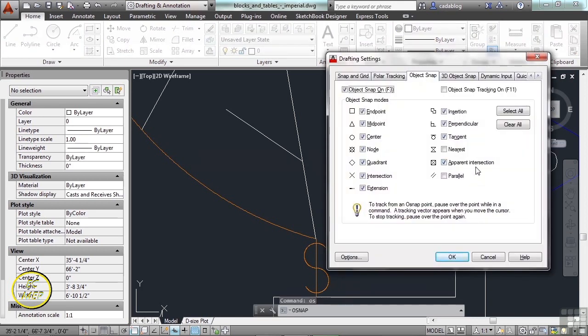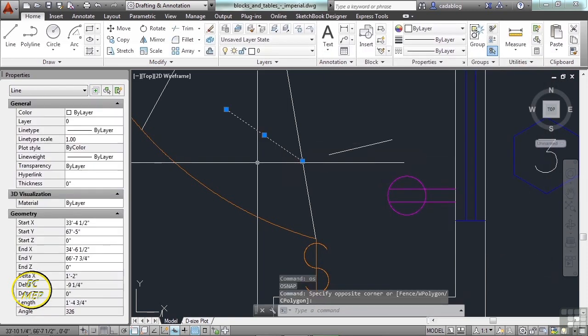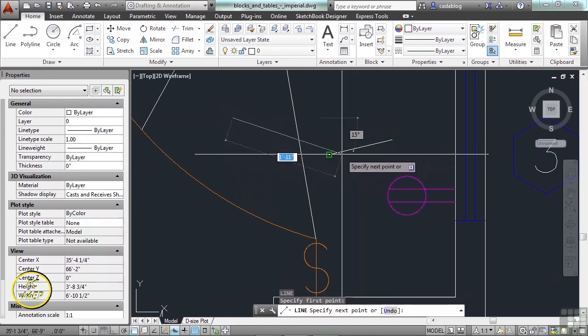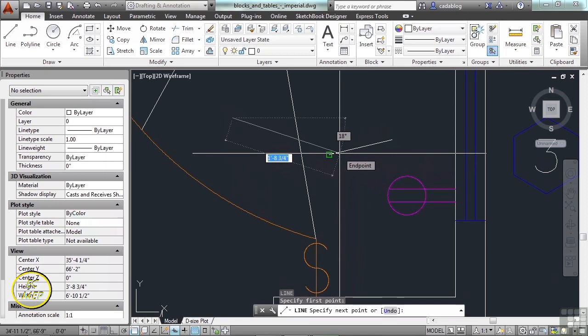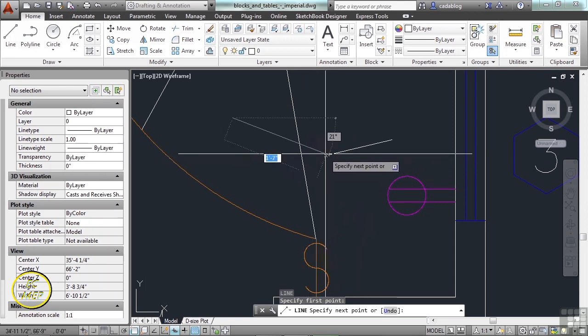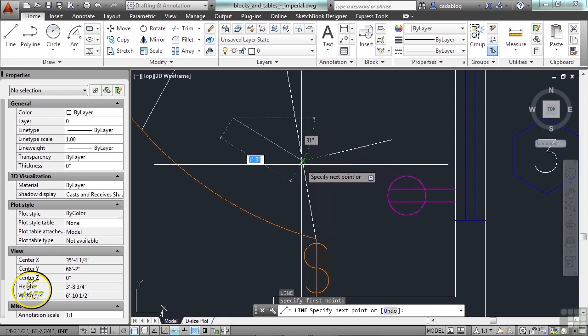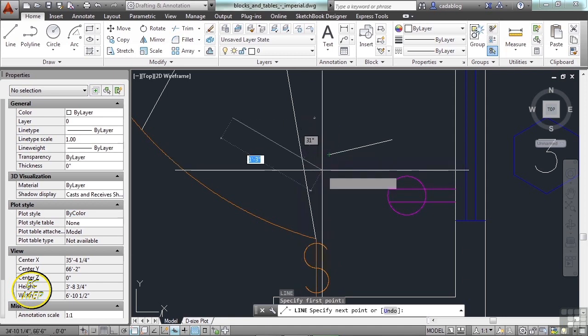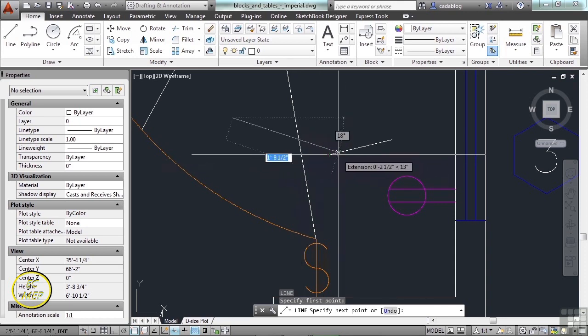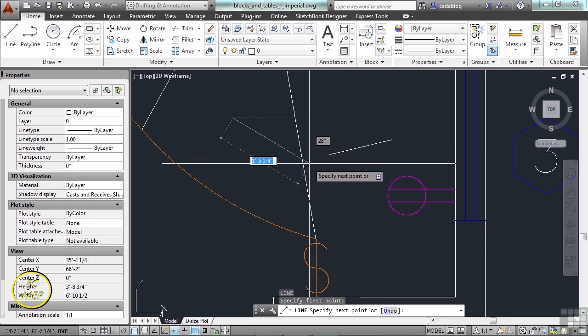Now, it can be very tricky to get it to show up. But let me show you again. Start a line. Now, I've got to kind of pick the line. Pick it and hold it. I mean, not selecting with my mouse, just hovering over it so that the O snap glyph comes up. Then go to my next object. I kind of got to grab them both. And now I can get to it. It works best if you pick your first point first, and then you pick the line that can be extended or that would be extended with it, in the case here.